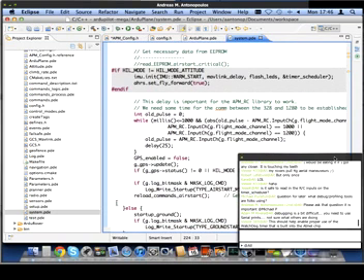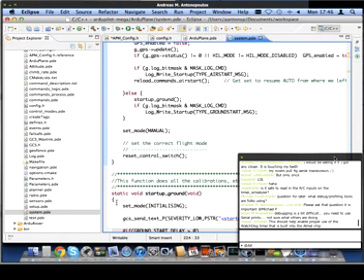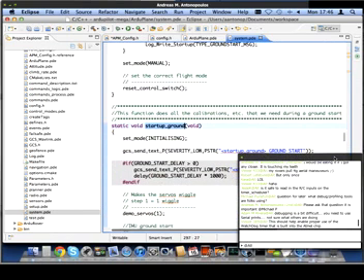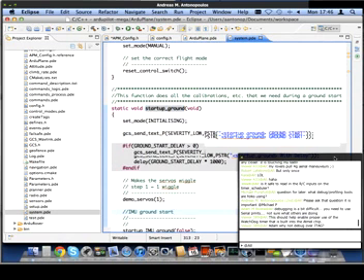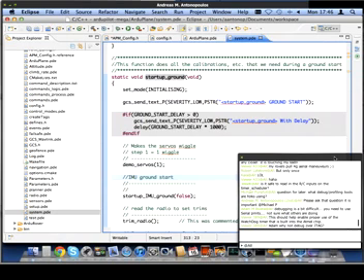So then down below that, we do the ground start. The ground start does the calibration. So we see the startup ground call there at the bottom of the screen on Andreas's screen. Startup ground is the rest of the code that gets called when we know we're on the ground. We're not doing an air start, and it calibrates all of the sensors, and that's what blinks the LEDs while it's getting the level, the 0 point on the gyroscopes for 0 rotation.